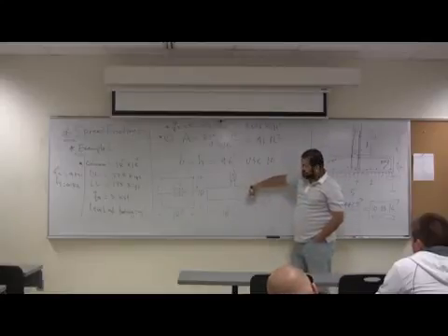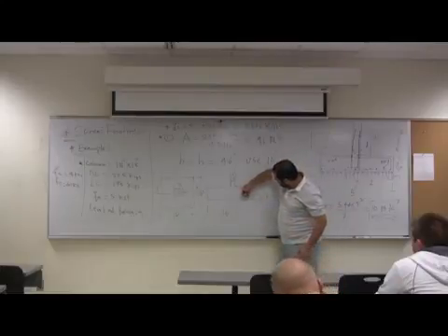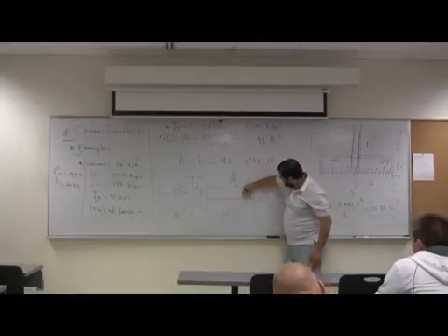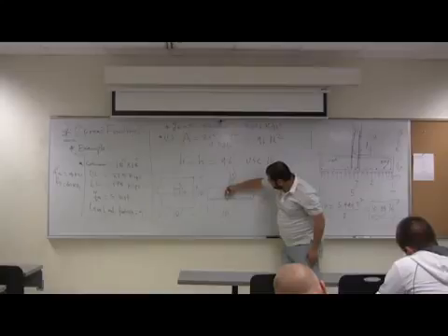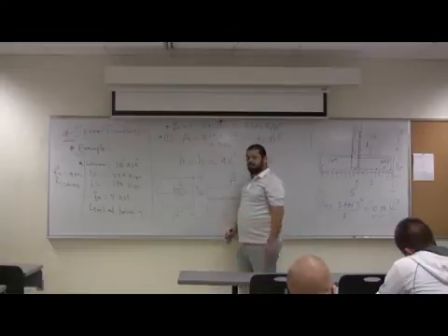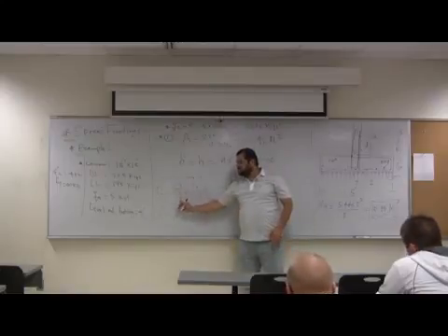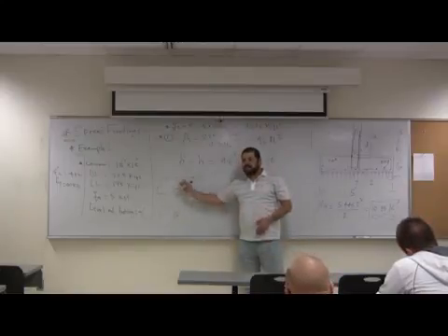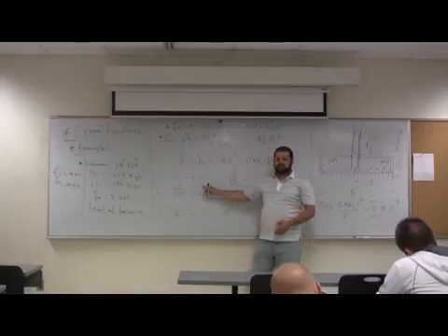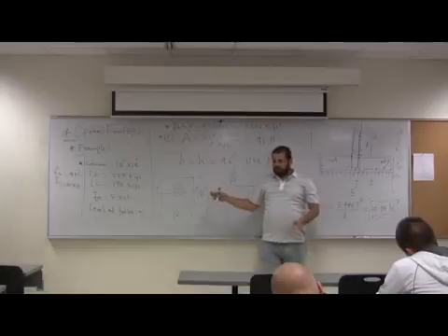There will be reinforcement. You think the reinforcement needs to be in both directions? Yes, of course, so there will be reinforcement needed in each direction. So this and that. And they are both flexural. You know what's the assumption in the single column footing? That the footing is fixed at the face of the column in each direction. So the footing is fixed here and fixed here. Okay?